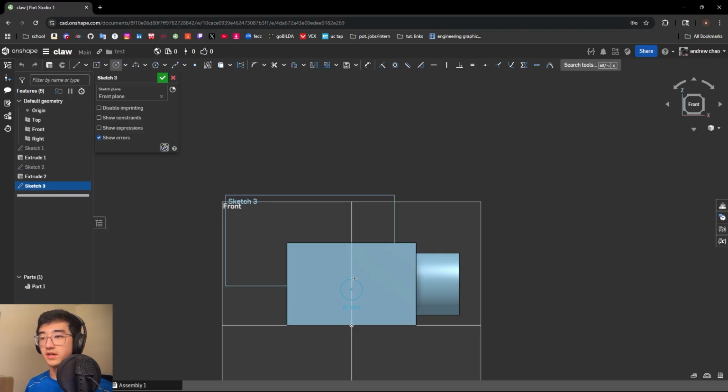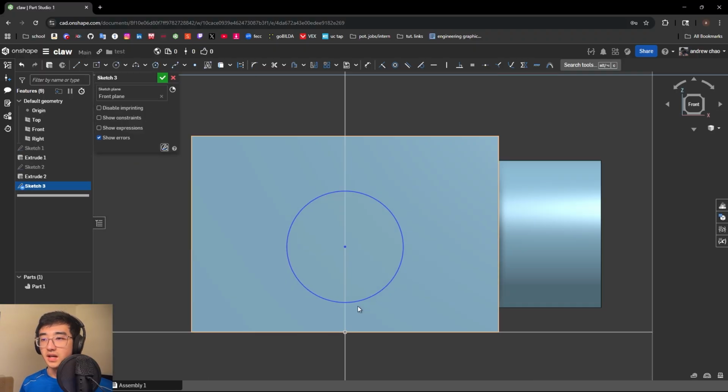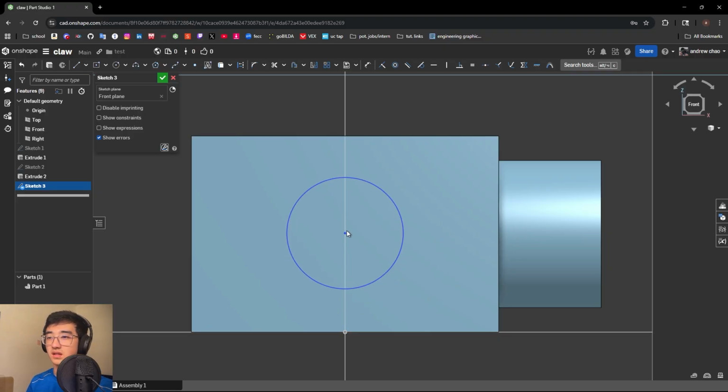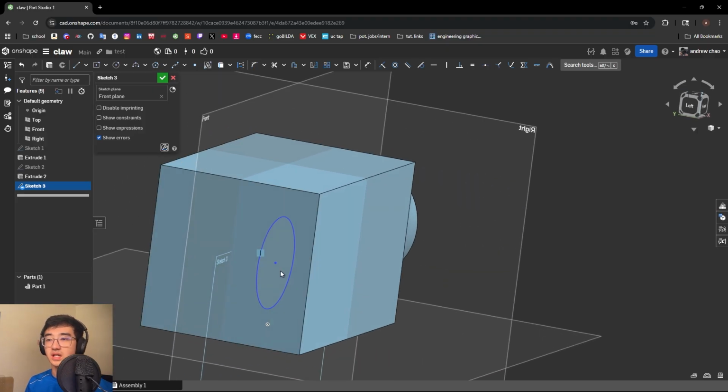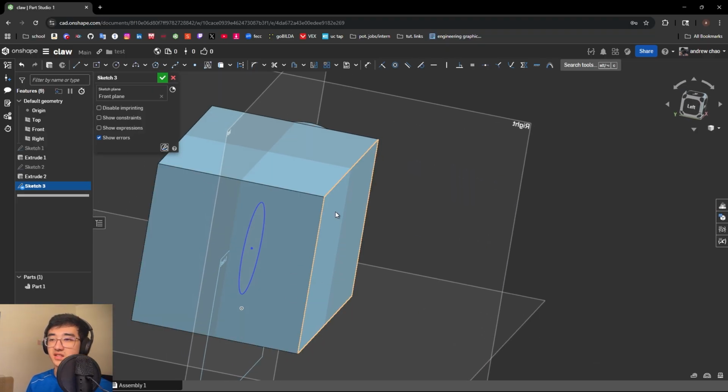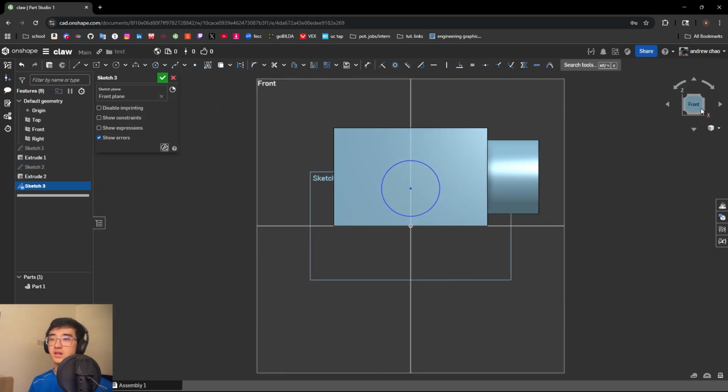so over here. At first glance it doesn't look like this circle is perfectly centered with this box, and for some reason it's not allowing us to snap. It's doing that because we're not exactly on the same plane as this face over here, so there's nothing to constrain. So we're going to force our own constraints on there, and that's where all of these tools come into play.